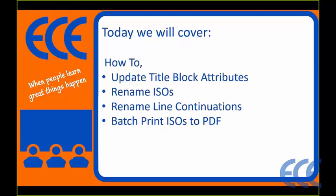your ISOs. So if you have a bunch of title blocks you need to update with the process conditions or specialized information, the revision, something to that effect for each ISO, we can do that through an Excel spreadsheet and post-process the ISOs to have that information in there for you.